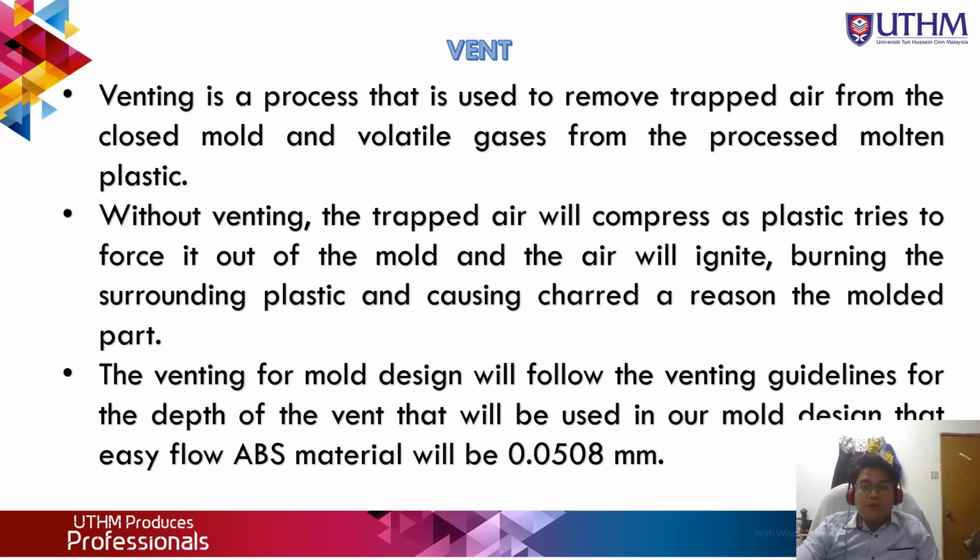Venting is a process used to remove trapped air from the closed mold and the volatile gases from the processed molten plastic. Without venting, the trapped air will compress as plastic tries to force it into the mold, and the air will ignite, burning the surrounding plastic and causing char erosion to the molded part. The venting for our mold design follows the venting guideline for the depth of the vent, which for easy flow ABS material will be 0.0508 millimeter.